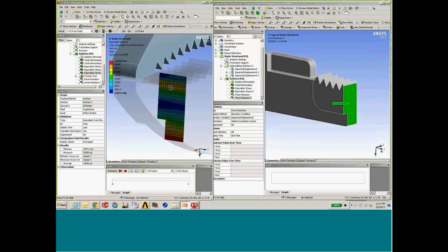The important items to keep in mind are, A, make sure you've saved those nodal forces during both the global and the submodel solution. If you can put the cut boundary planes in one geometry model, if you're using Design Modeler, place them at the very top in the beginning of the process, and then you can very simply grab those, make sure you import those into the global model on the mechanical side, and you can use those to do the surface interpolation. Otherwise, you always have the option to just recreate a coordinate system in mechanical to evaluate what's happening on those cut boundaries.